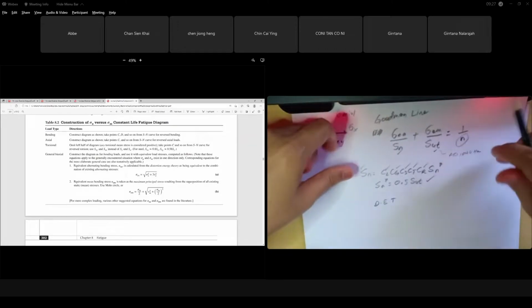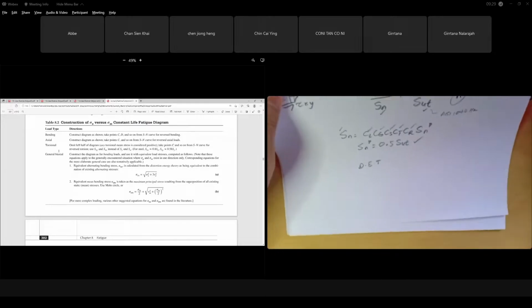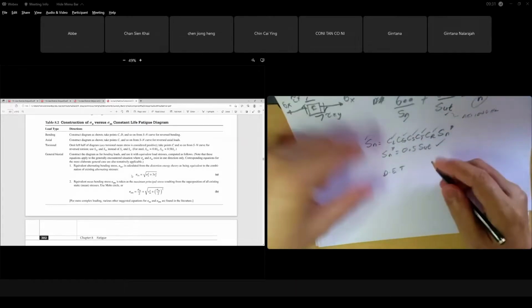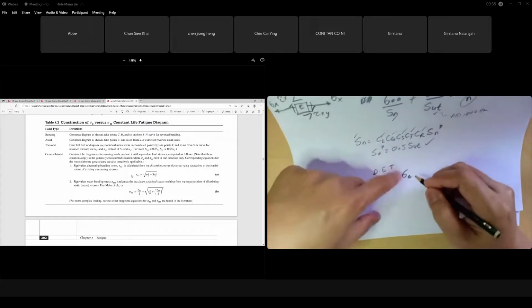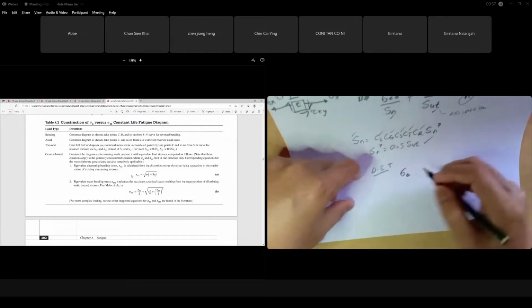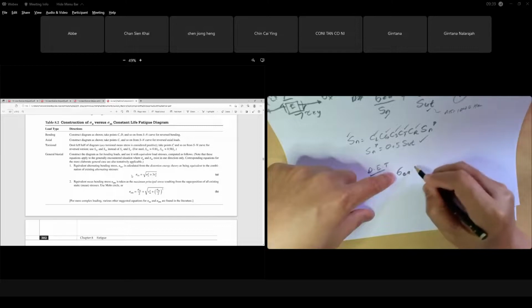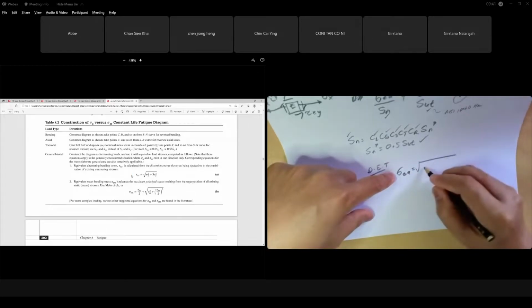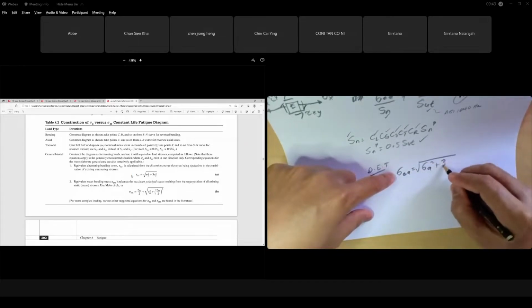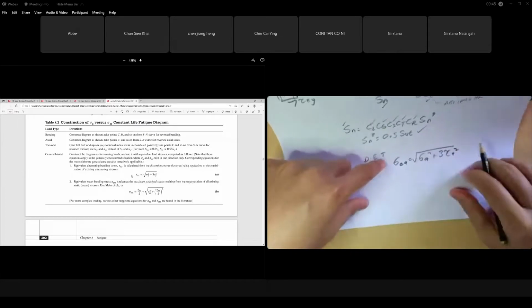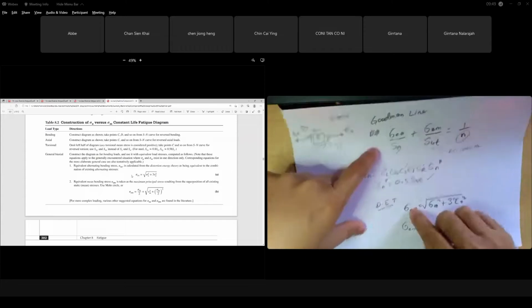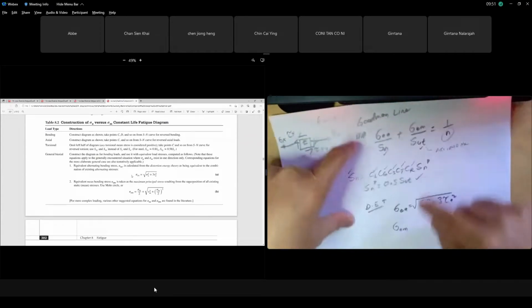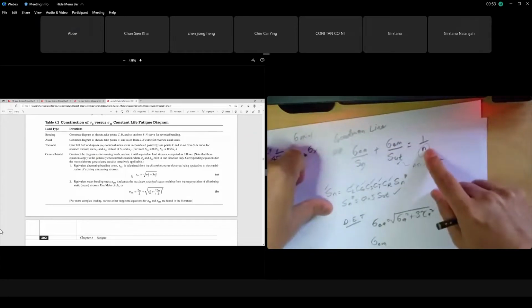For biaxial stress, if you look at this equation in your textbook, you have to find sigma EA, the equivalent stress amplitude. Sigma EA equals the square root of sigma amplitude squared plus 3 tau amplitude squared. And sigma EM, the equivalent mean stress, we have to put at the denominator, then we can get the safety factor.